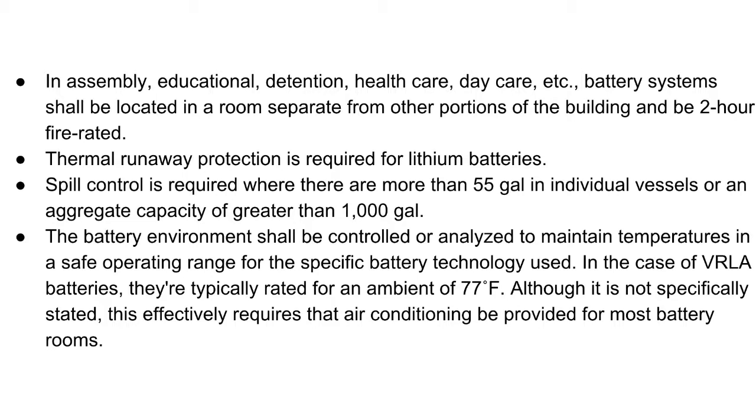Even so, we see the fire code saying, if that battery is rated for 77 degrees, it may not be part of the National Electric Code, and it may not be part of the manufacturer requirement to say it's rated for 77 degrees but can handle up to 90. If you're going to keep it in a 90-degree environment, it needs to be rated for 90 degrees.